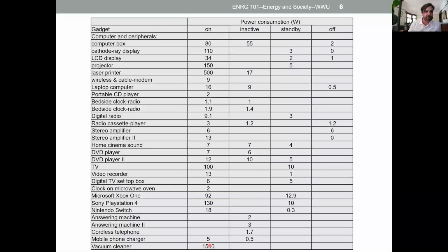Why 1500 watts? Remember when I turned the kettle on? Anybody remember how many watts it drew Friday? Yeah, 1375. And so that's about the max that you can pull from an American outlet. The max you can pull is 1500 watts. And usually it's slightly less than that because the appliances protect themselves and your circuit breaker from getting all the way to 1500 watts. And so if you want to get the maximum amount of heat into your water as quickly as possible, your kettle is going to run at like 1400 watts.